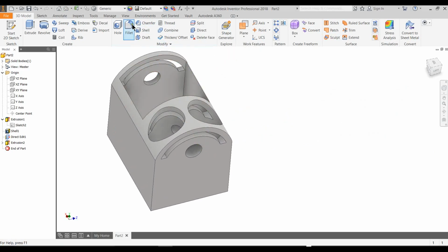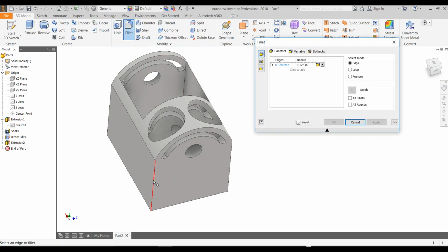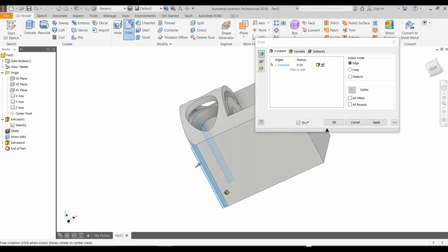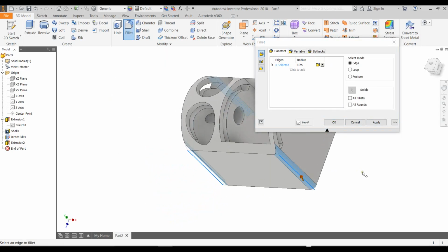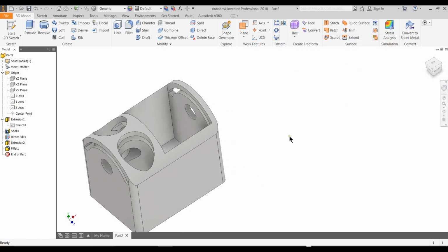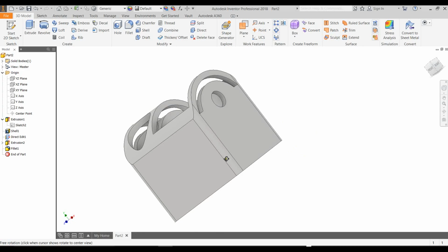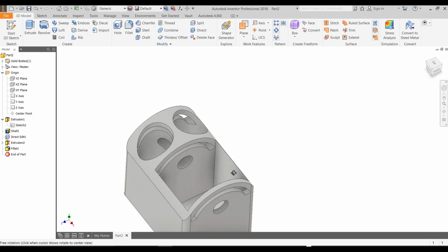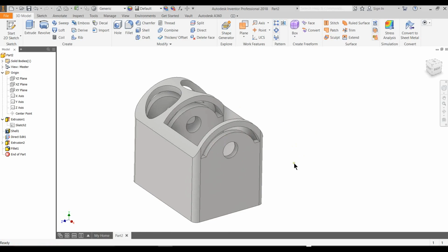We've got the fillet edge command that we can use. So again, you just click on something, you can define the different radiuses. So maybe we want to pop that up to 1/4 inch and go around and just round off the corners a little bit for this guy. See if that... Okay, so just walk around all these tools, play around with it, and make something fun, something that you can try out the 3D printer with.